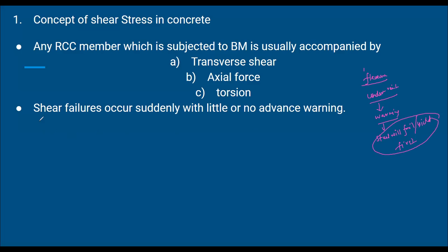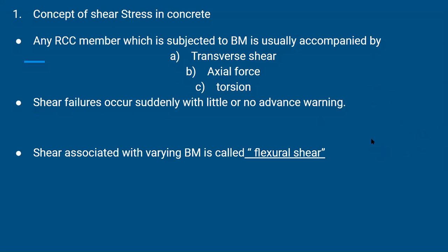So by then you will be getting enough time to save yourself. But the problem is with the shear failure. Shear failure will occur suddenly. Okay? Suddenly. So we should be very careful while designing for shear failure. That's what I'm talking about.